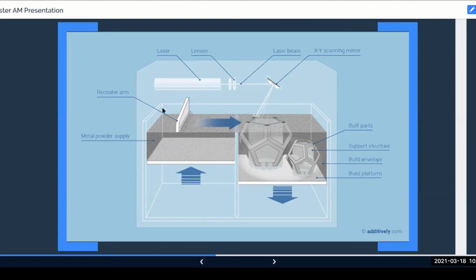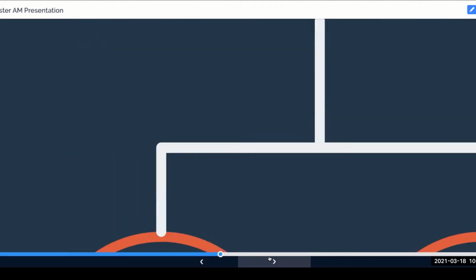And you push a thin layer of powder over the top. It's super smooth, like a sheet of paper. We fire a laser, we melt together that powder. It obviously bonds to itself, and we create a part. So we start to do this layer by layer. Lo and behold, we get really, really complex geometries with actual polymers.